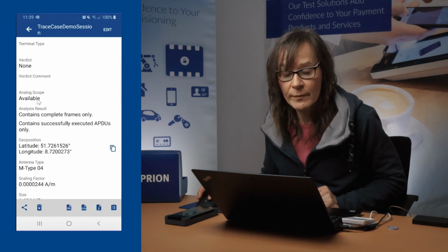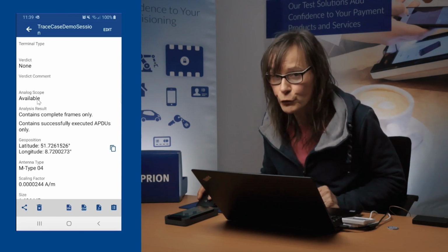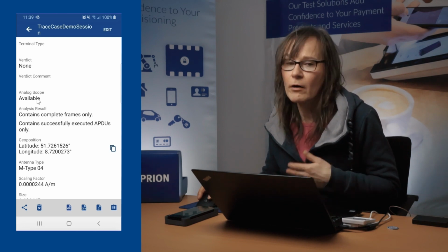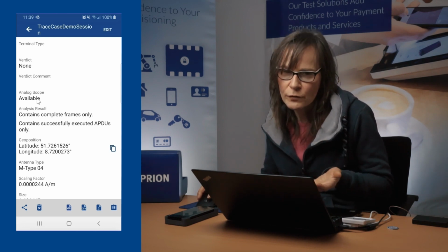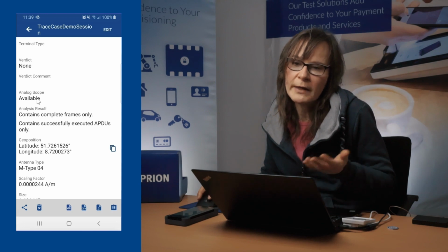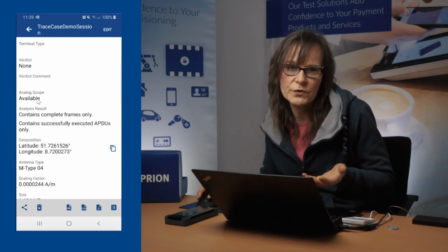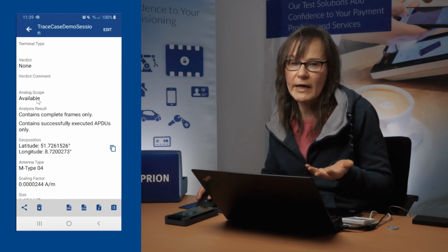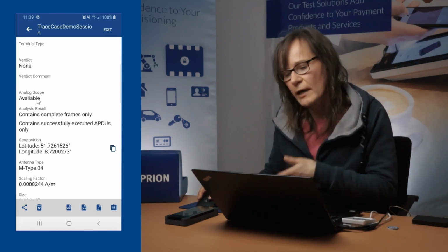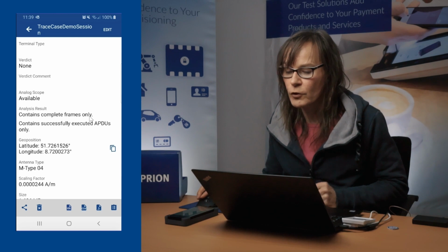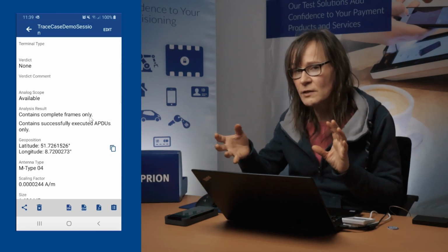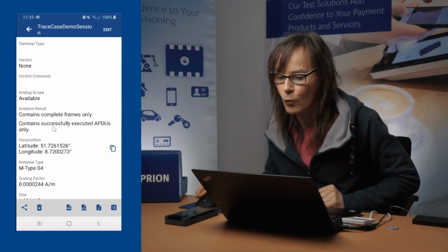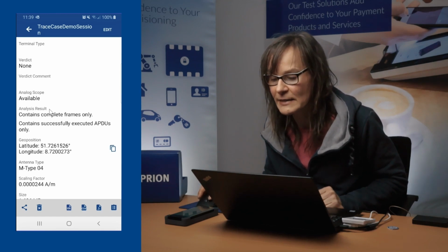And in some situations, it's very helpful to do so because sometimes you might even have error handling so that the protocol looks fine, but you might still have some issues on the physical or signaling level, and it gives you more information about errors which might occur. For contactless, there are a lot of dimensions in which you can communicate, so it's very, very helpful to have the analog scope for error detection and error analysis.